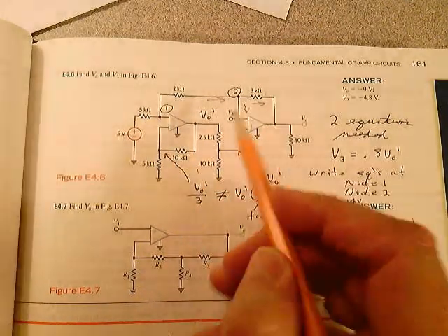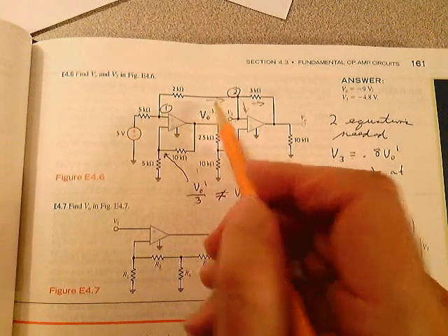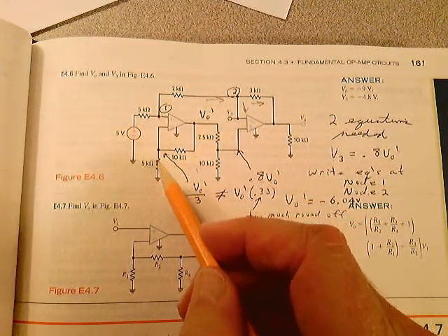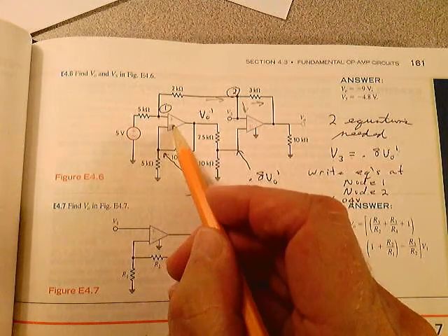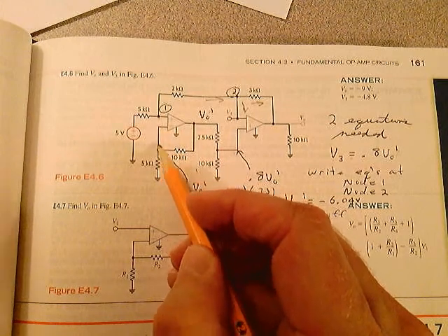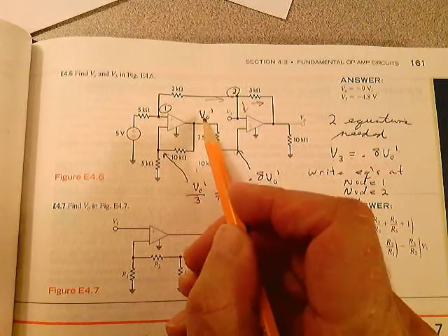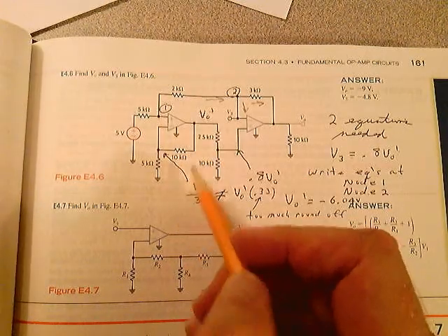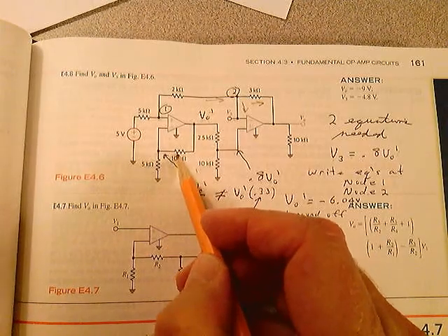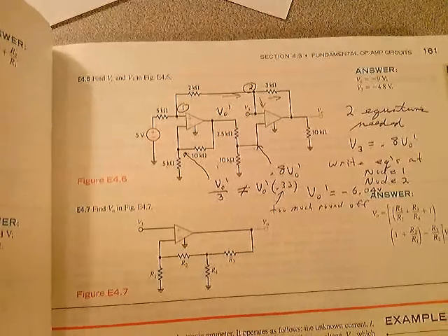So what you have to do is refer to this as V out prime. I called this the dummy variable V out prime because this is V out. If this is V out prime, this is just a voltage divider at this point. This is an infinite resistance from here in, so you can just ignore it. So what voltage is at this point if that's V out prime? Well, that point is just V out prime times 5K divided by 5K plus 10K. That's the same circuit as if you would have something that looks like this.